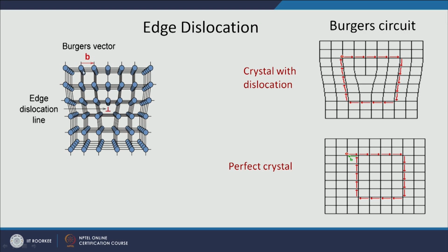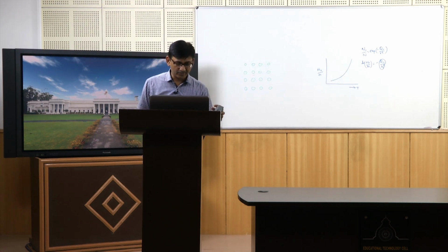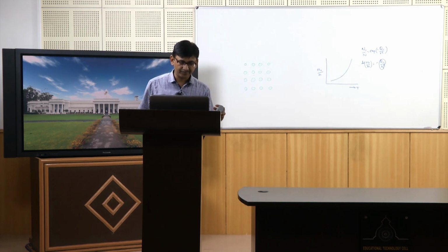After a certain distance you will see that all are still nicely arranged on both sides, but where the dislocation is ending there is a large amount of straining in the material. You can see that this dislocation is going in the direction of the projection here on the slide. So, this is the end of the dislocation and it is going into the material like this. If I want to see it in 2 dimensions, it will look something like this.